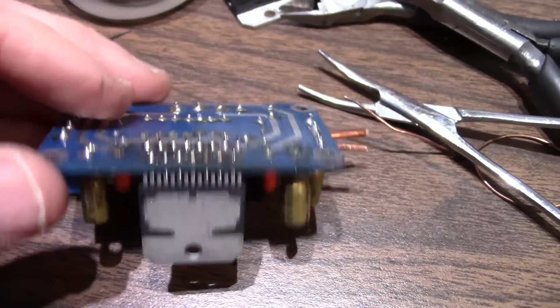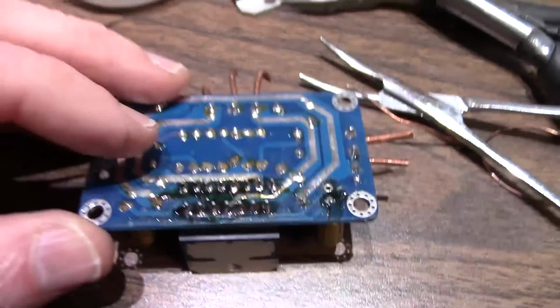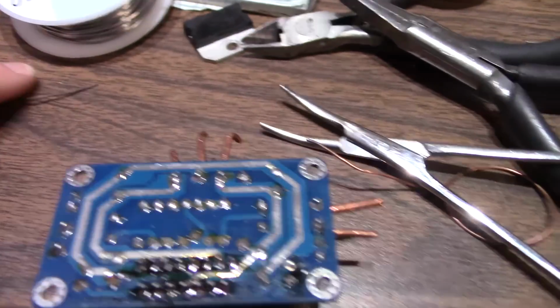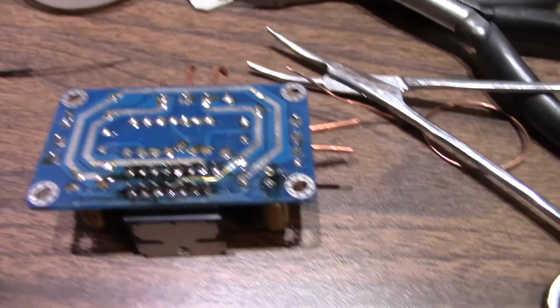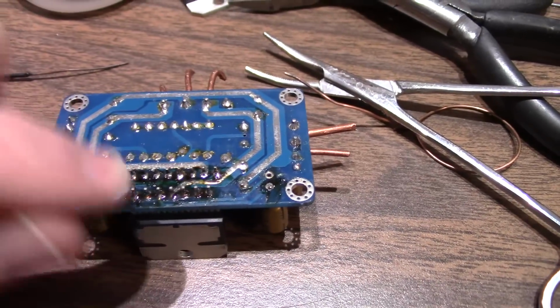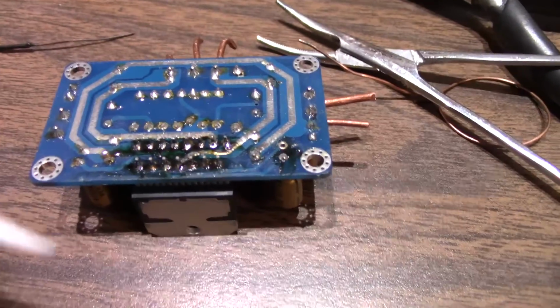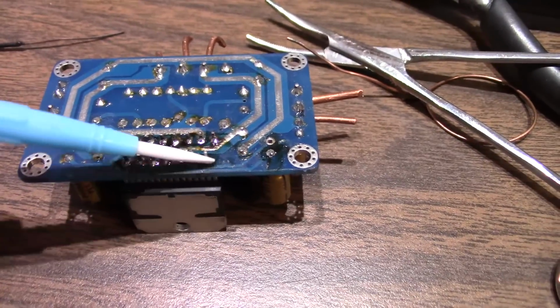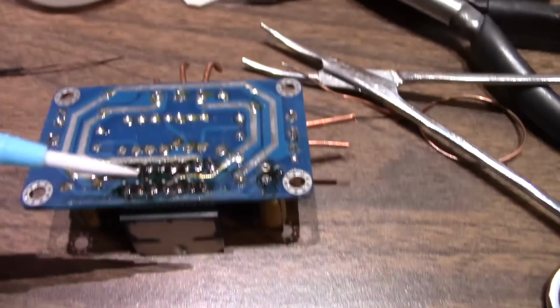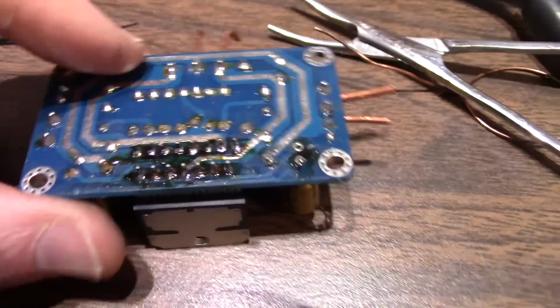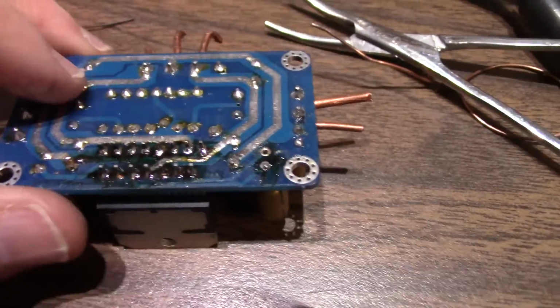Well, that was nightmare fuel. That chip would not go in there. I had to take a piece of copper wire at the right size, heat it with the iron, and run it up and down each hole until I cleared enough solder out, because even just using the wick didn't get enough out. But I got it in. Screw it, I'm not going to clean the flux off.